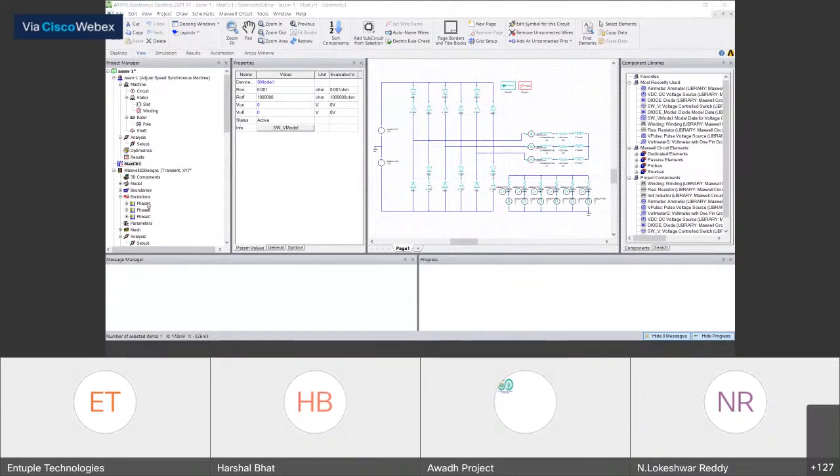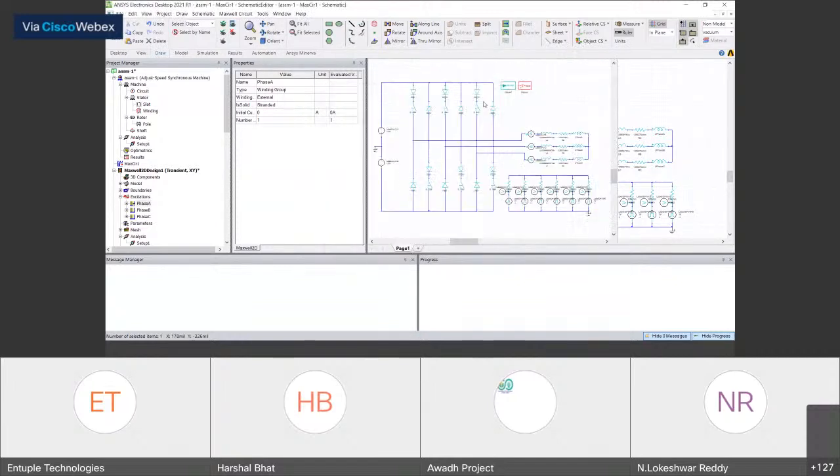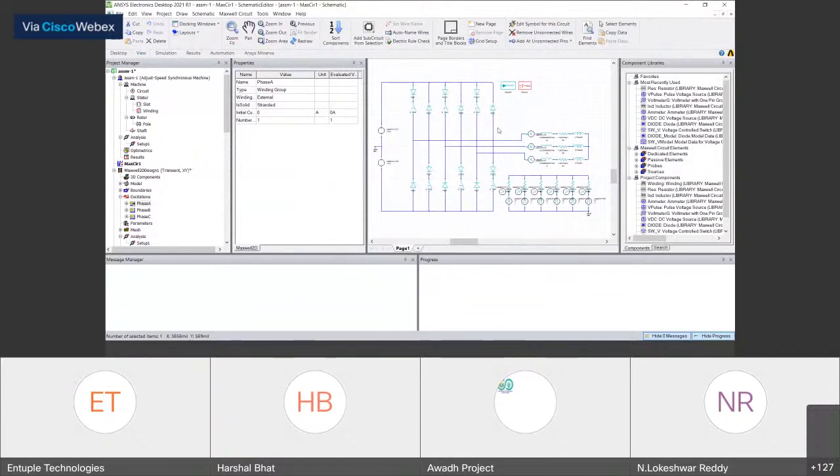Just like here we have specified that the type is external, you can also have current and voltage sources here. And those current and voltage sources can be time varying. They can be constant values, equations, data sets, or external circuits like this. Whatever kind of source you want, as long as the source has a unique value at every time step and is a continuous function, you can use it. So all time varying inputs and time changing properties can be done.